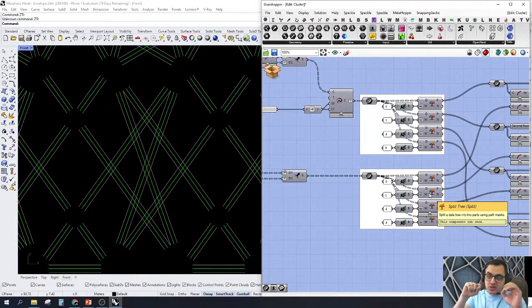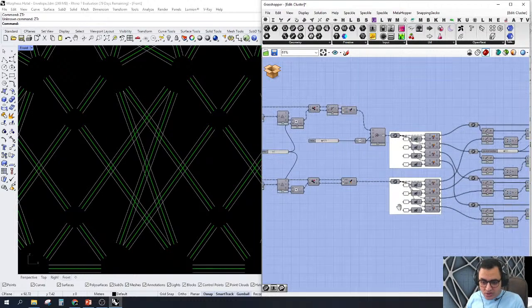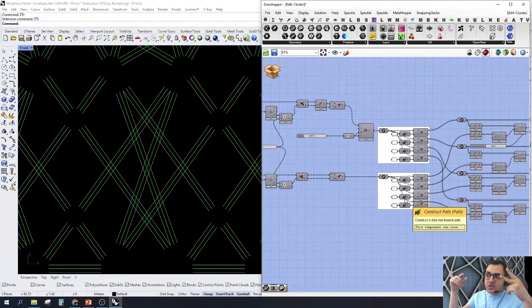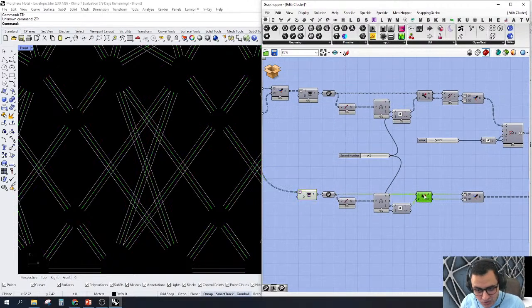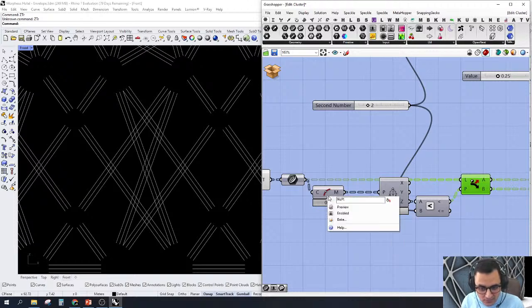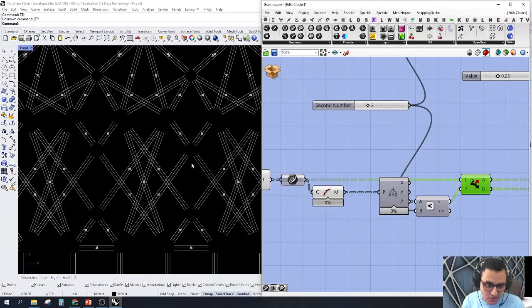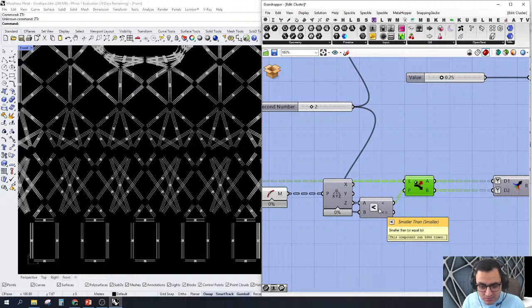There are 2 curves that are offsetted already, and for each curve we wanted to grab the 2 closest curves around it, because some of the curves are offsetted in one direction of the surface, and it doesn't fit in the other part. That's what we wanted to do. So basically, we grabbed the midpoint of each curve, and sorted them based on their height.